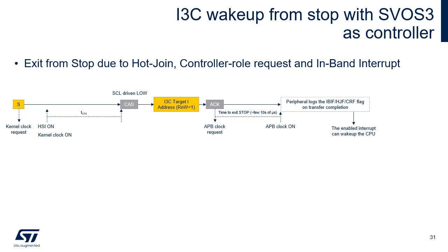On a detected start condition on the I3C bus, the SDA line is detected to be driven low while SCL is high, as controller, as initiated by an external I3C target device for a hot join, inbound interrupt, or controller role request.